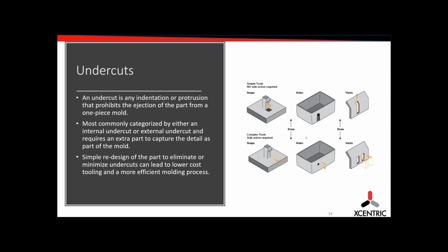What is the effect in geometry of cooling your part too fast? Thermal deformation. You're going to experience some warpage, especially if you have a larger, flatter part with not adequate ribbing. That part, for the box for instance here, is going to want to shrink in and almost bend into itself. Bow in on these sidewalls.